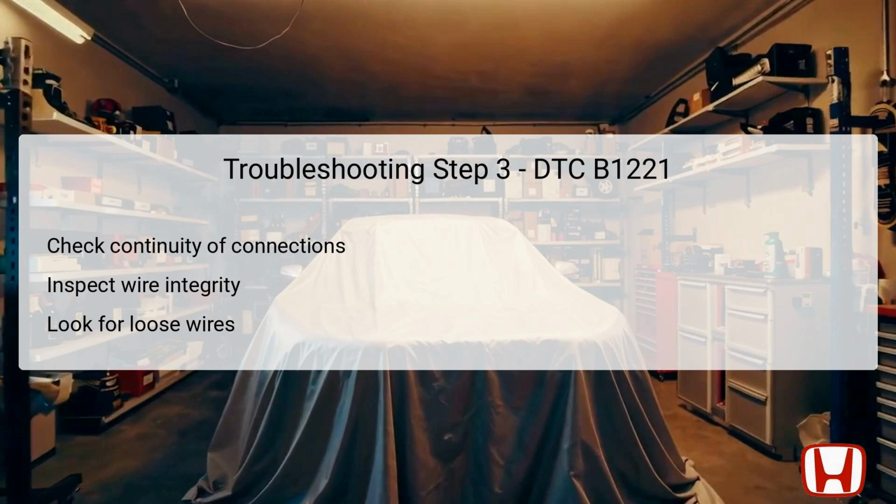Pay special attention to any points where wires may be twisted or bent, as these areas are prone to damage. If continuity is inconsistent or absent, this could indicate issues that need to be repaired. Document any findings, as this information will be critical in deciding your next steps.